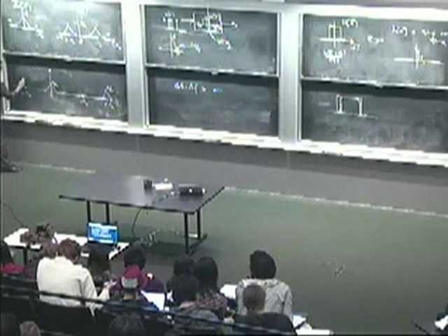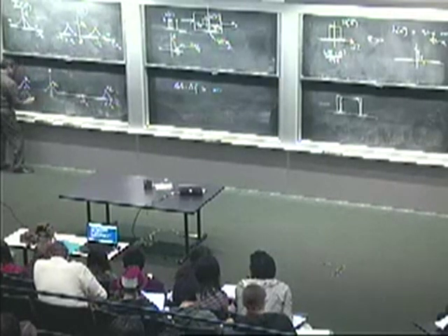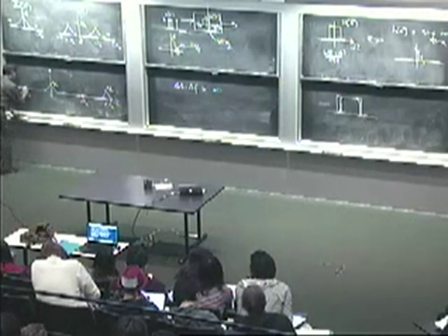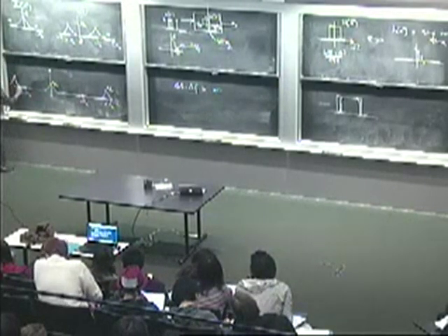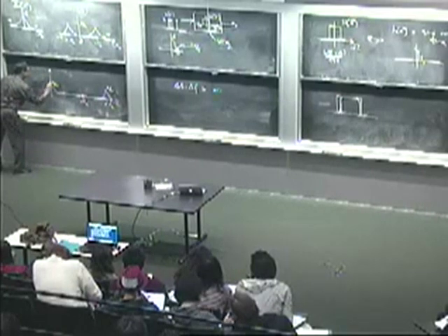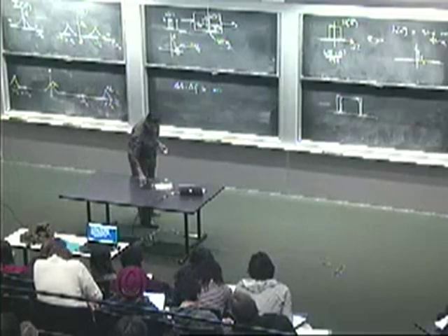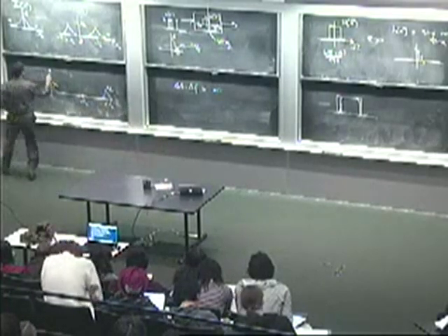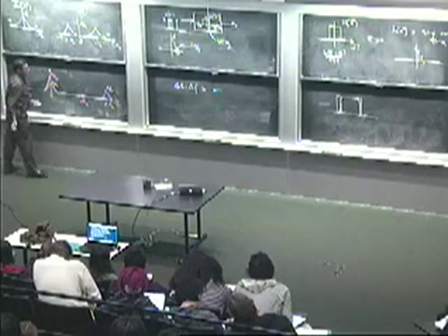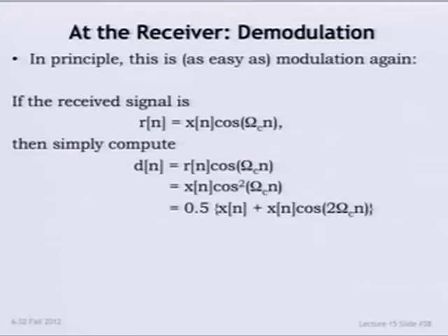Okay, so I've got the N over 4 piece here. Sorry, I drew it in the wrong place. This is going to end up at minus 2 omega c. And the replication here, there's going to be a second one sitting here at the origin. So the net effect at the origin is that I get the original spectrum, but scaled by a half. And then I get vestiges of this, if you like, centered at twice the carrier frequency.